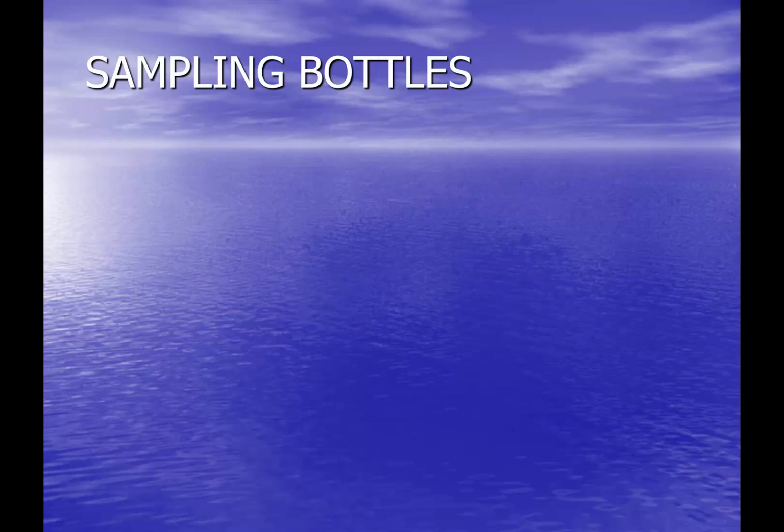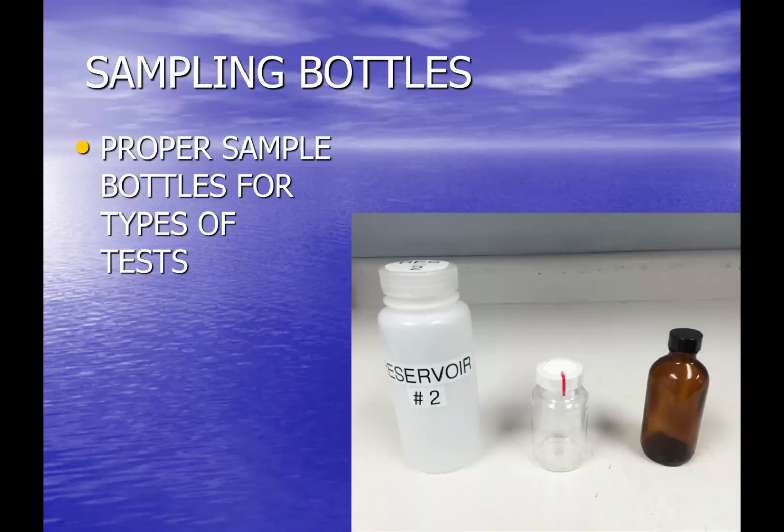Take a quick look at the bottles that we typically use for sampling. It's important to use the proper sample bottle for different types of tests. The picture you see here demonstrates a few of the bottles we use for sampling. The one on the left is a 500 milliliter bottle. We'll use that for samples that we're doing tests for chlorine, for ammonia, for nitrite. All of the physical analysis we do, whether it be color, odor, pH, turbidity, those all come from that 500 milliliter bottle. Next to that in the middle you see a 100 milliliter bottle.